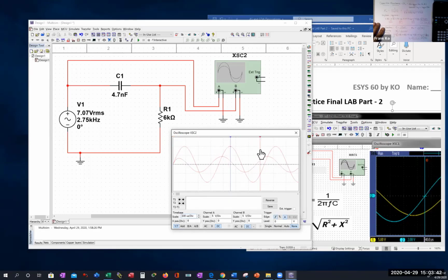Bring this guy in and move this over to here. Looks like the peak of this guy. And for channel B, isn't that very close to what we guesstimated as 4.4 volt peak? Okay, so channel B at 4.4 volt peak, channel A at about 10 volt peak. Now that's how you can also use these cursors to confirm the peak values.